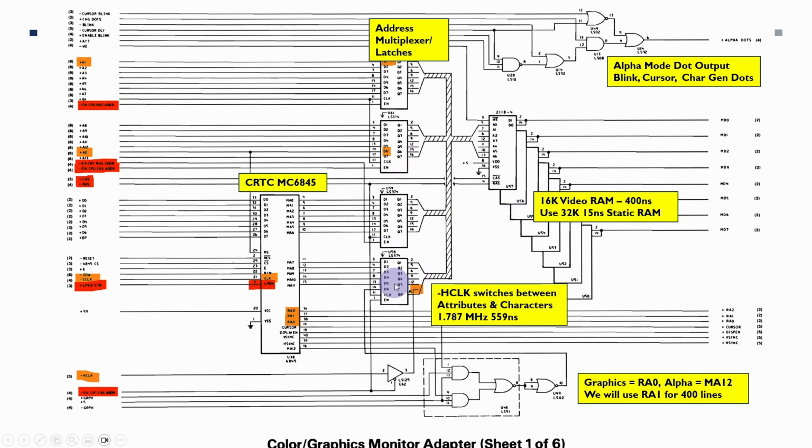And the key thing here is that because we're using dynamic RAM, the address had to be latched in this particular way, because the video RAM had row address and column address strobes, so we'd only give the address lines half at a time. We do the columns and the rows separately, and that's the reason why these two latches had to be available here.